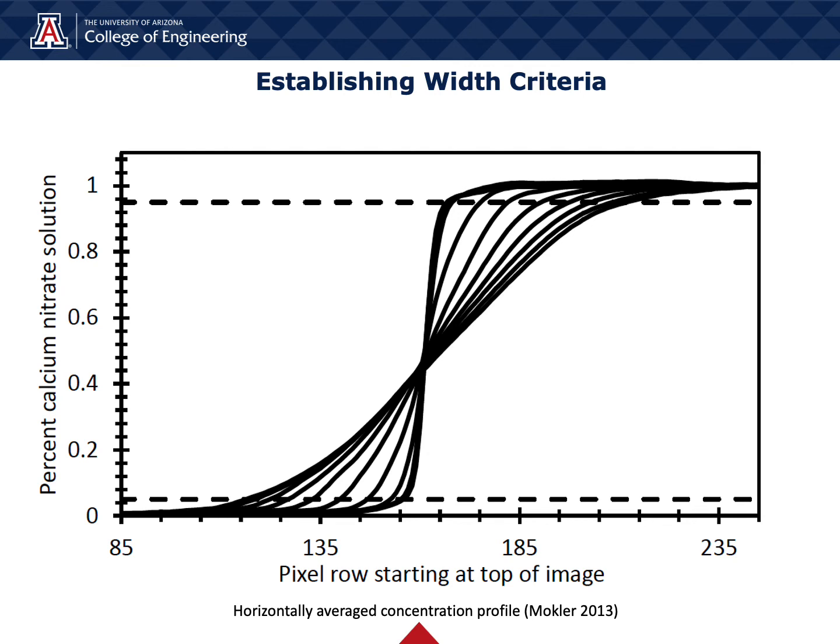As the mixing region develops and grows larger, this concentration profile stretches horizontally. You can see this in the image on the slide. We can calculate the mixing width a variety of ways, including linear regression or an integral definition like the one given in the equation for h on the previous slide, which performs an integration on the curves you see here.